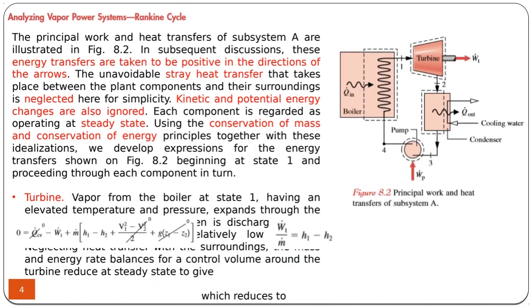So we are interested in the power plant itself, not the whole thing, but only the vapor cycle itself. In a vapor cycle, as I said, we have a boiler in which we add heat. Then, as the heat is added to the liquid water, here we have liquid, the liquid water becomes vaporized, and at the exit of the boiler, it's a vapor. So as it passes through the turbine, it rotates it, giving us a turbine work.